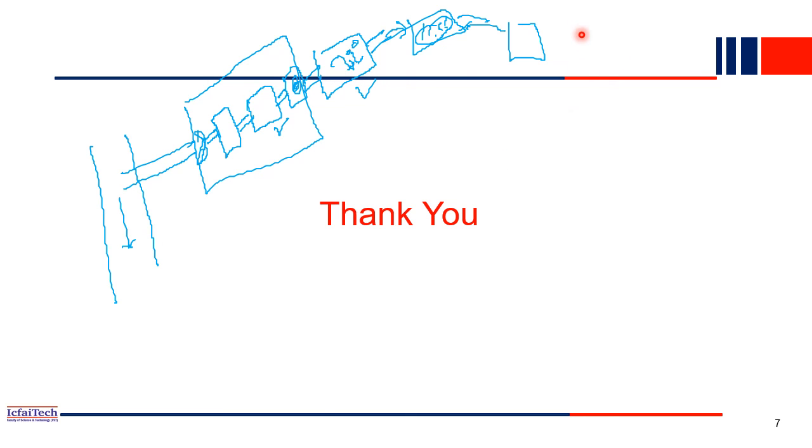So now you understand the entire flow diagram of a water treatment plant. We collect the water, first is screening, then the aeration tank, then the primary sedimentation, then the flocculation chamber, the coagulation chamber, where rapid mixing happens. Then it will go to secondary sedimentation and rest for some time. So the clean water will go to filtration. After filtration, water will go to disinfection, where we kill the bacteria, right? Then the water will be purified for drinking and distributed to households. So that's the actual sequence of steps that we'll be covering in this course.